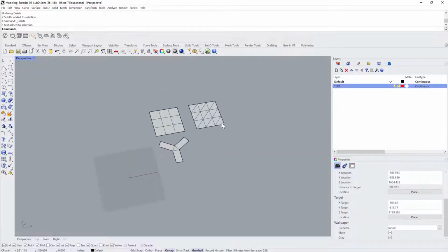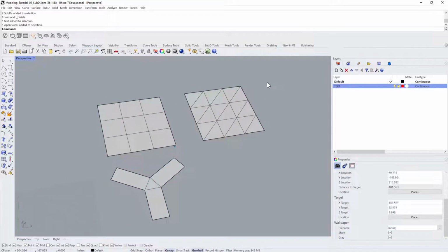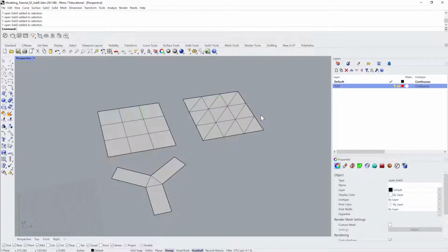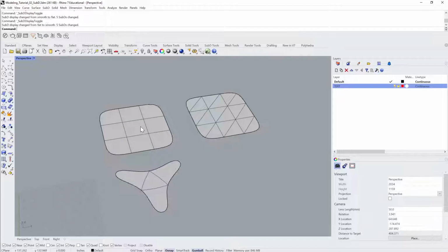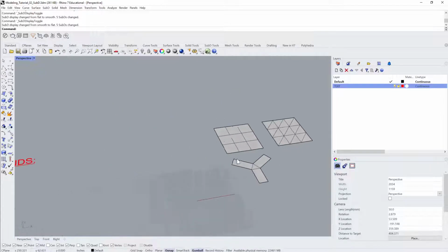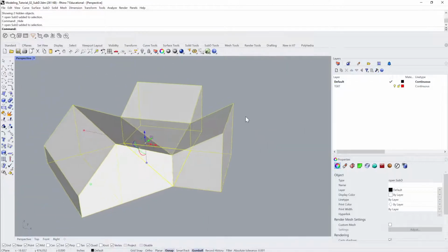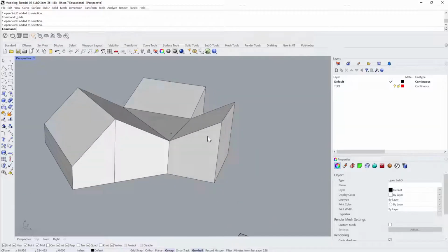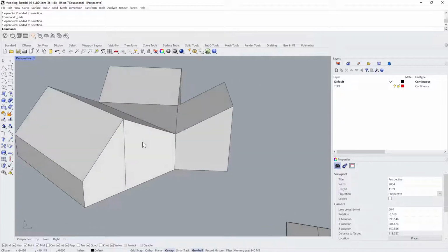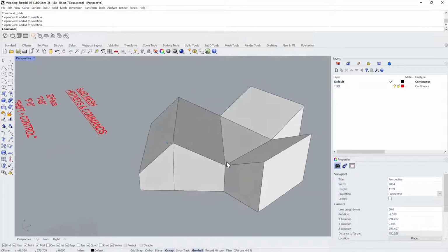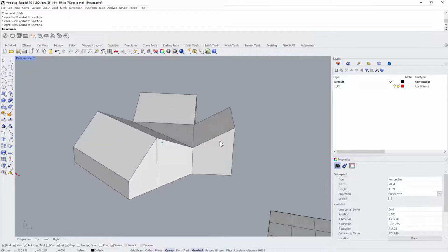All right, now let's look at SubD, good SubD topology. Now these are all SubD surfaces, and I know that they're SubD surfaces because when I select them and I look at the bottom right here, I see Open SubD. And if I hit Tab, I can see that all of these things curve. Now, if your final massing or the final geometry should be faceted geometry, then you don't have to worry about what I'm about to tell you as much.